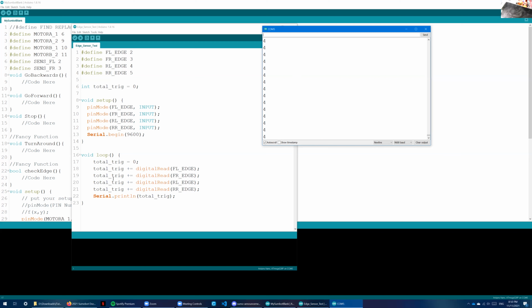But for testing, first of all, it doesn't match the actual Sumobot surface. The Sumobot surface is quite textured. This is quite reflective, and I think it'll still show a 0 if I do this, right? Let's see what happens. Yeah, see, it thinks it's white when I put that on, which is not what we want. So just hot tip, if you're trying to debug, use a matte black surface.